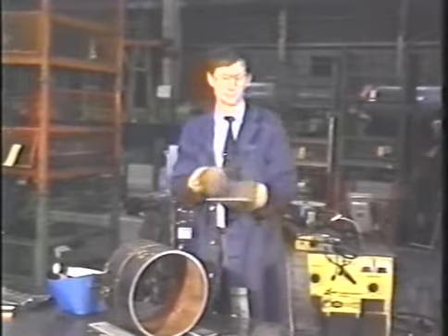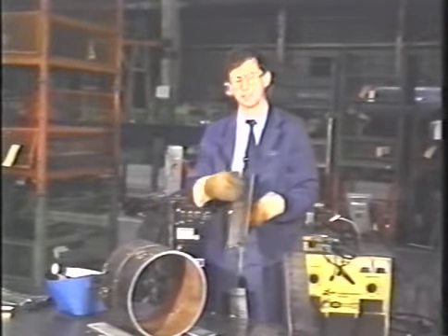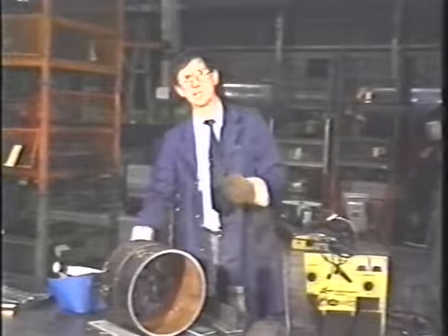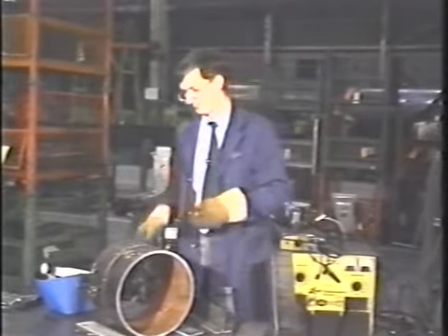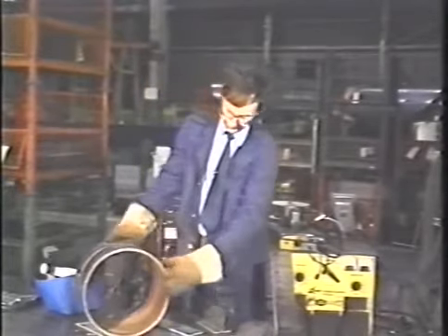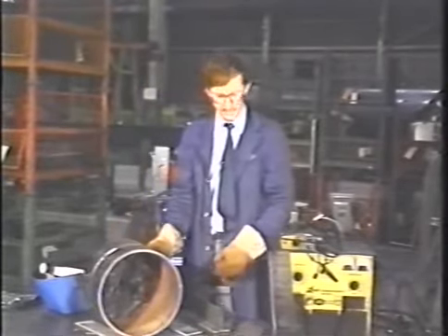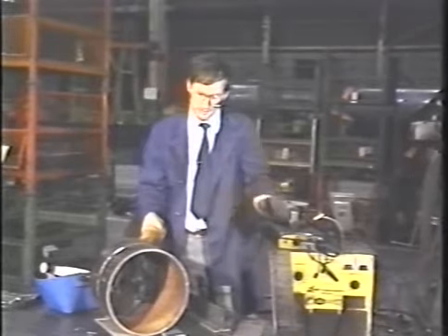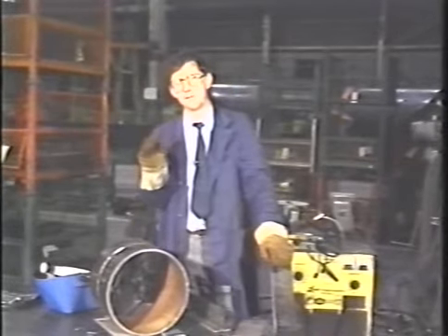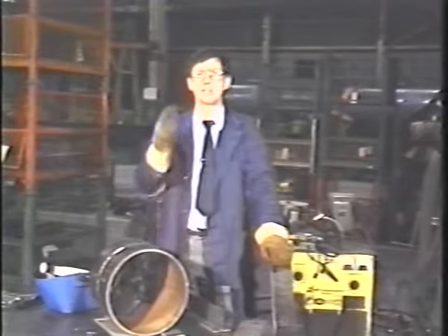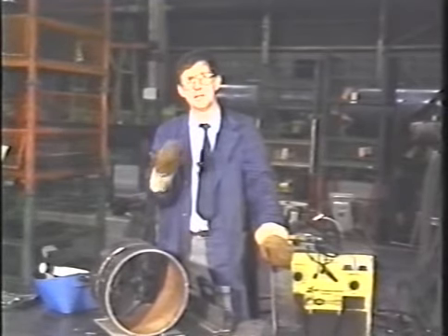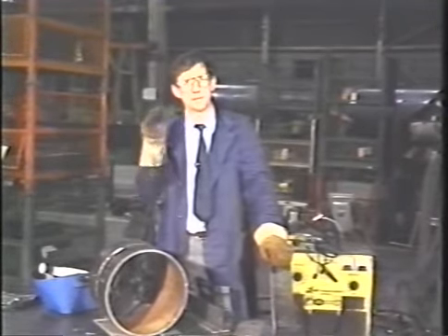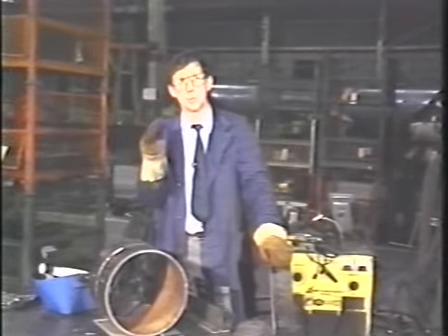Applications like 10 gauge plate, vertical up. Applications like 16 gauge material, fillet weld. How about a root pass in a pipe? These are basically short-circuiting applications. Remember, the simple rule is if it's less than 1/8 of an inch, or it requires vertical up or vertical down, or you're welding a gap, you simply think of short-circuiting welding.